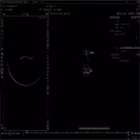Let's get rid of the wrangle. Nobody wants to use wrangles if we can do VOPs. Technically, the way this works is all these nodes just encapsulate vex functions. So in reality, this add is just laying down a piece of code, a snippet of code, into a program in the background. Same holds true for this constant.